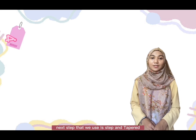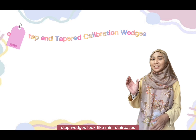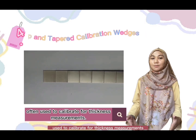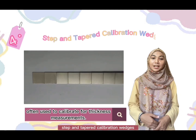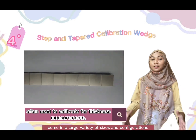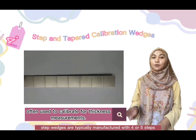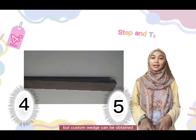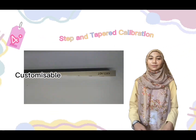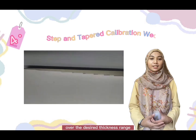Next type that we use is step and tapered calibration wedges. Step wedges look like mini staircases. They are often used to calibrate for thickness measurements. Step and tapered calibration wedges come in a large variety of sizes and configurations. Step wedges are typically manufactured with 4 or 5 steps, but custom wedges can be obtained with any number of steps. Tapered wedges have a constant taper over the desired thickness range.